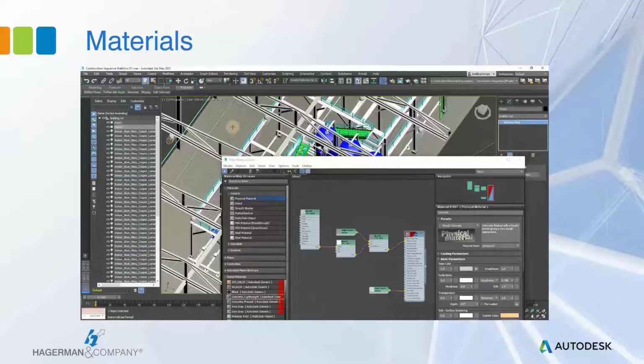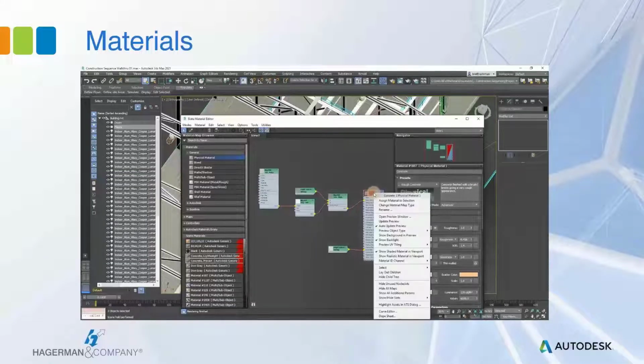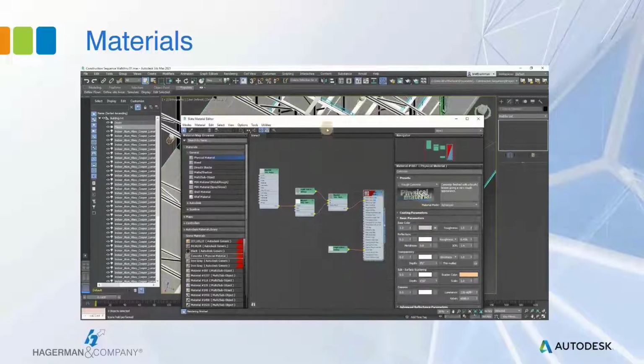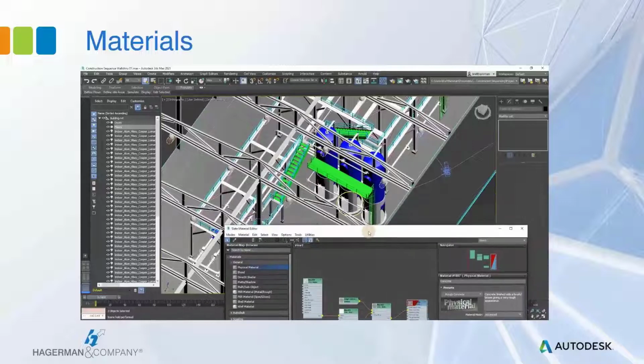So I'm going to select the floor and the walls. And then I'll go back into the material canvas and right-click on the material and then assign material to selection. And you'll see that change reflected in the model as soon as you do that. So you can override any material that might come in from the source model.